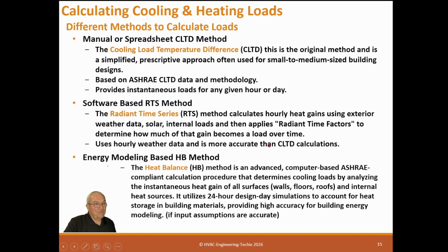Energy modeling is based on the HB method, the heat balance method, which is an advanced computer-based, ASHRAE-compliant calculation procedure that determines cooling loads by analyzing the instantaneous heat gain of all surfaces, walls, floors, roofs, and internal heat sources. It utilizes 24-hour design day simulations to account for heat storage in building materials, providing high accuracy for building energy modeling. That assumes that the input assumptions are accurate. And of course, if you put garbage in, you get garbage out. So you have to be careful with that. And this energy modeling is all based on HB methods. So we'll go through that a little bit.